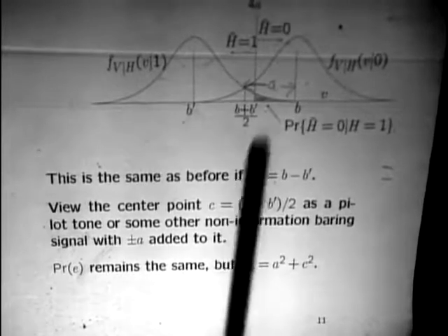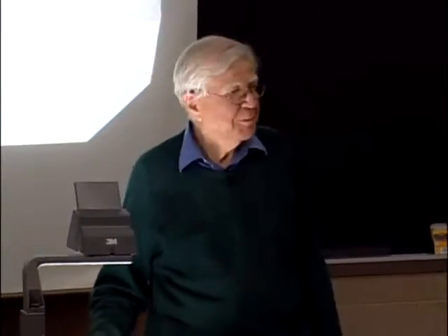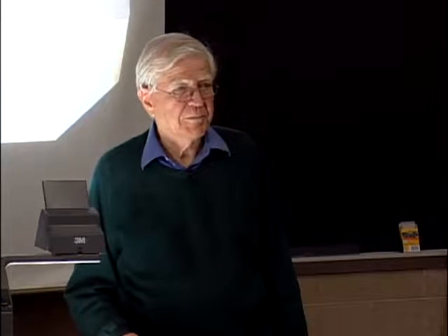It's that same underlying idea. So anytime you use non-antipodal and you shift things off the mean, you can see what's going on very, very easily. You waste energy. It might not be wasted. You might have to waste it for some reason. But as far as the communication is concerned, you're simply wasting it. So your energy per bit changes, but your probability of error remains the same.